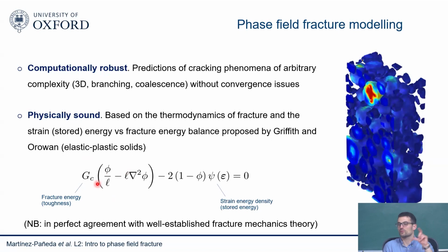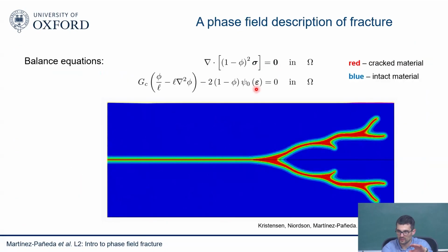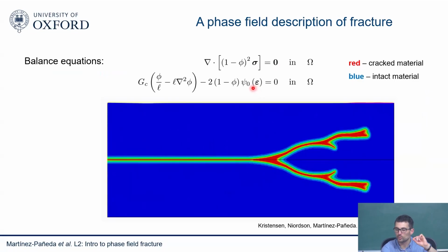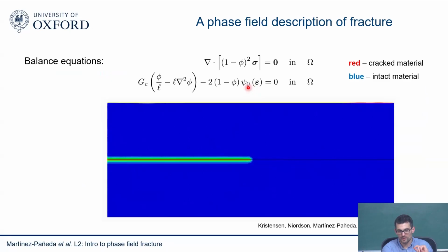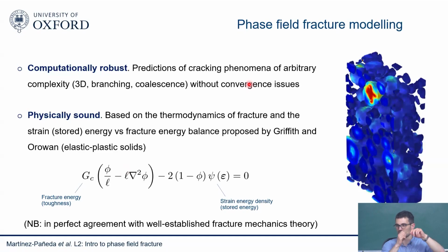And so that's on the physics side of things. On the computational mechanics side of things, there are some benefits related to the fact that we are solving the damage as an independent variable and with a different PDE, because you add some flexibility on the computational side of things. I will discuss that later on. But the short answer is that it's more robust because you solve for the damage variable independently, so you get convergence much more easily. And the other one is that it's connected to fracture mechanics. I don't have 4 or 5 parameters to fit. I just have one, a fracture energy, that I know before I run my simulation. So it's more predictive in that sense, I would say.